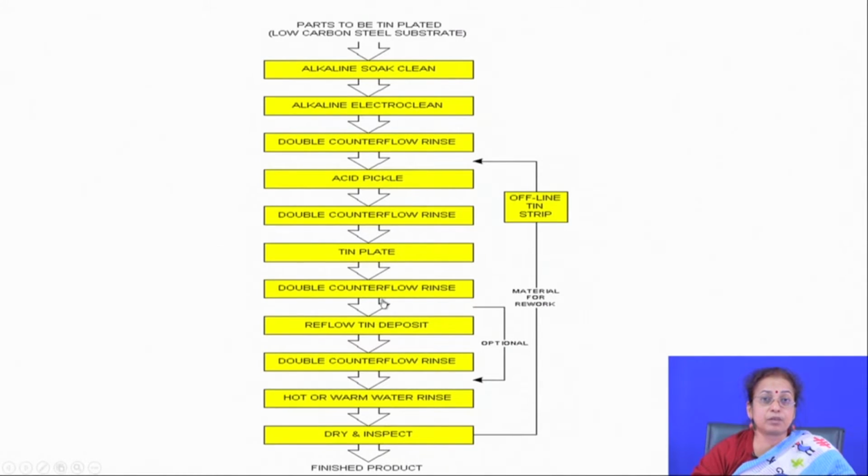So, this has a lot of roughness, and the surface finish is not so good, so you have to go for a finishing operation. On the other hand, if you go for electrodeposition, you get a highly mirror polished surface, and naturally the thickness can be as low as you wish. So, particularly for corrosion resistance applications, electrodeposition is the preferred technique over typical hot dipping.